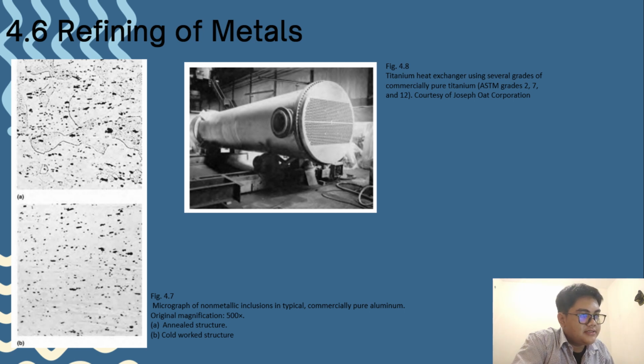Very high purity metals are often not useful for any type of structural application. For example, gold that is 99.999% pure is impractical, even for use as chains or pins in jewelry. However, some other material specifications require exceptional refining techniques. Silicon, as well as germanium and other metals used in the semiconductor industry, must be produced at controlled purity levels equal to or exceeding less than 1 impurity atom for every million atoms of pure element.